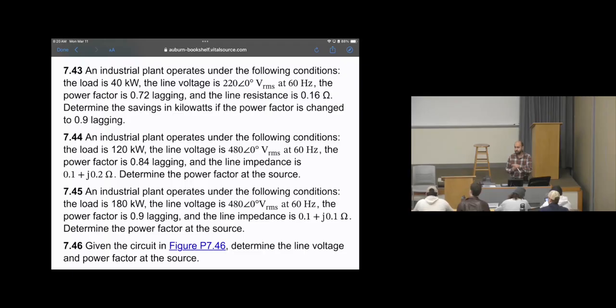If you see the unit volt-ampere, then it's apparent power, S. If the unit is var, it's reactive power. So it's very important. Sometimes it's just playing with the words. Here it's kilowatts; maybe some other questions use var, or volt-ampere.